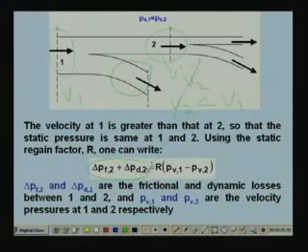Okay, that means whatever is the frictional losses from point 1 to 2 is equal to the static regain factor R multiplied by the velocity pressure at point 1 minus velocity pressure at point 2. Okay, PV1 minus PV2. PV2 is always lower than PV1. That is how you select the dimensions of the downstream duct. Okay. So, you find that because you are balancing exactly the drop in velocity pressure with that of the losses, the static pressure at point 1 and 2 will remain same. That means PS1 will be equal to PS2, right.